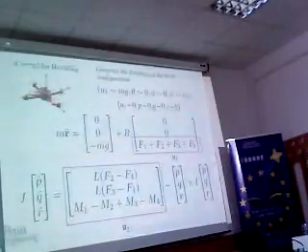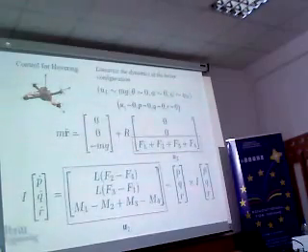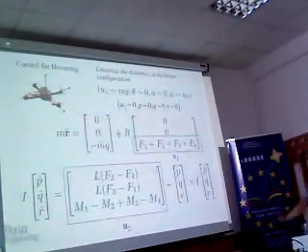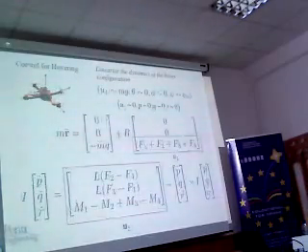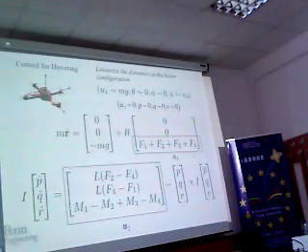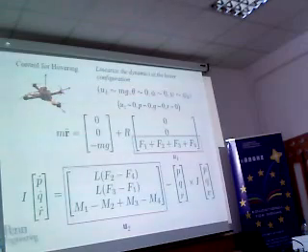Likewise, the sum of the thrust has to compensate the weight, but the yaw angle can be non-zero. And in this situation, you can see that the rotor stays in one point. So it means that the weight and the thrust are equal, so F1 plus F2 plus F3 plus F4 is equal to mg.